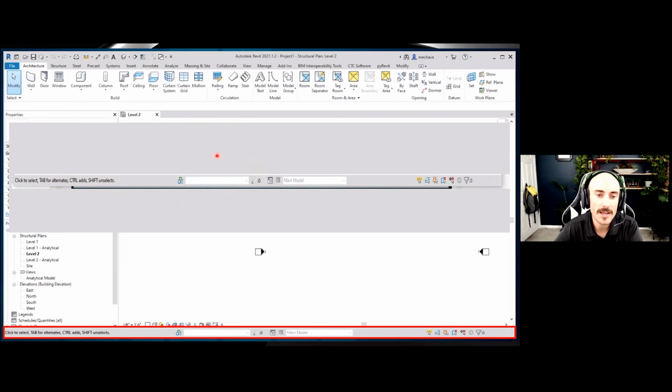To the right of that, you have your work sets. Now, work sets is probably a new term for you. You can write it down. There'll also be some things about it in your handout as well. But one great thing that Revit allows you to do is create work sets. This allows work shared enabled models.